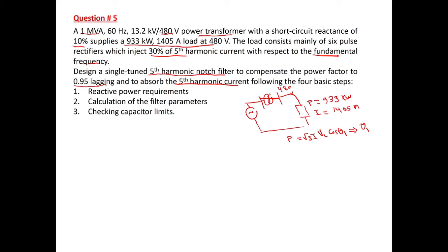And now he said that we would like to also connect over here a single tone filter. So we would like to connect with the existing system a filter that will take care of the fifth harmonic, and at the same time improve the power factor to 0.95 lagging.